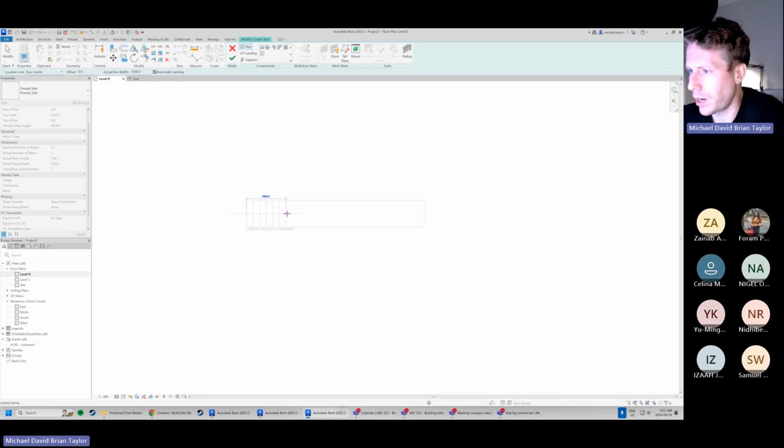If I start to drag over a little bit, we can see those numbers: 10 risers created, 17 remaining. So why don't we move this all the way up to about midway? Let's do 13 or so risers created and 14 remaining. Then, if we click once, we're going to do what's called a switchback stair. So we're going to click once and we should see the first little bit of our stair created.